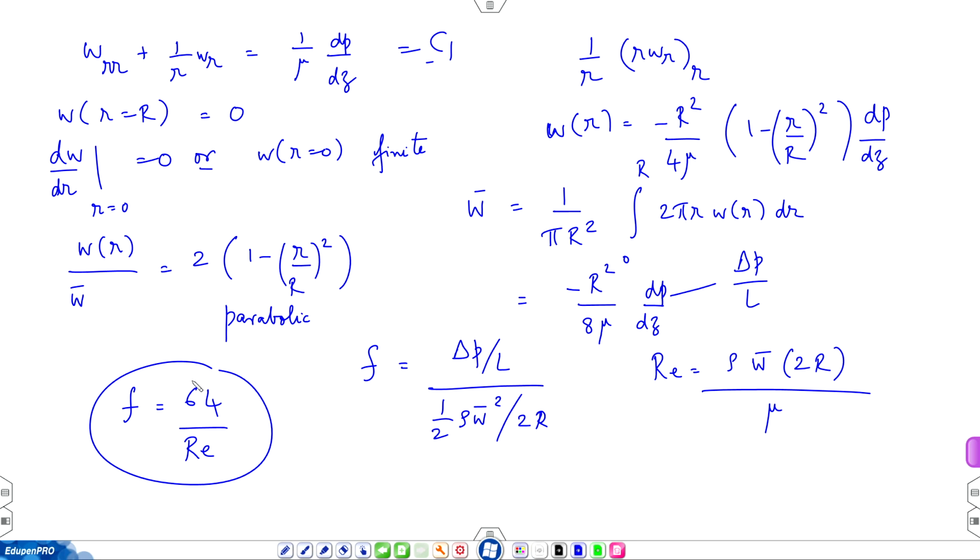So, here is an occasion for you to compare with experiments. What experiments? Moody's diagram. Is this result for air? Yes. Is it for water? Yes. Is it for oils? Yes. So, it is for fully developed flow, steady, incompressible Newtonian fluid with a well defined viscosity.